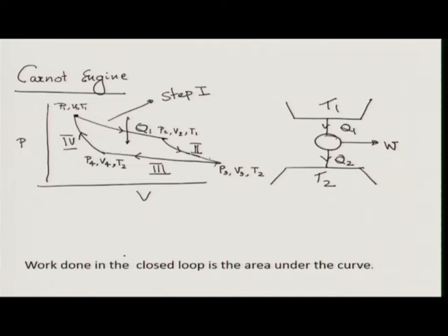Okay. Now, this process is adiabatic. You know, by looking at the slope, this curve should be very symmetric, which I could draw. Now, you see this is adiabatic. So, in this process there is no heat absorbed, okay, and this process takes it to P3, V3 and T2. So, it comes to the temperature of the cold reservoir.